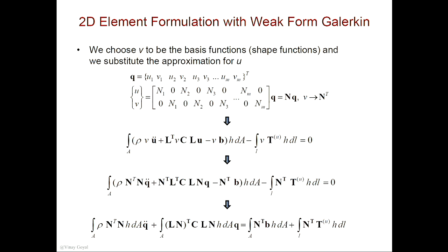I actually don't see any difference between the 3D. This can be applied to both plane strain and plane stress. The only difference is the constitutive law changes. This C changes for plane stress versus plane strain. Yeah? That's the only difference in the two formulations, right?